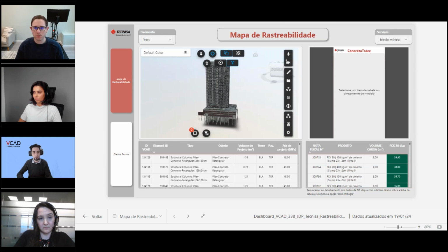So if you have an IFC or a group of IFCs or a group of Navisworks, then yes, it can be done, and you can federate them at runtime. So no need to do the work beforehand. You simply set it up and the viewer says, okay, I want to load this model and this model. And dynamically inside of the report, you can choose which ones to switch on and off.